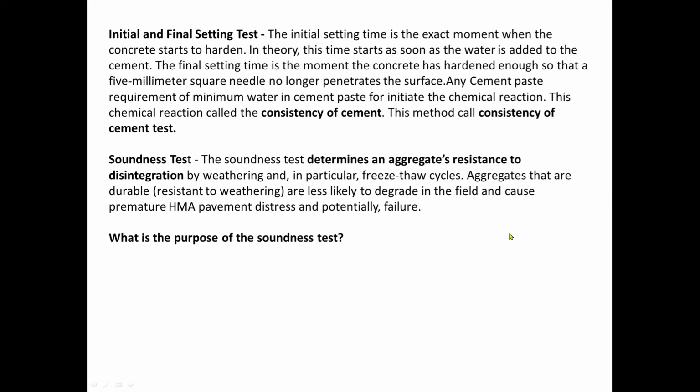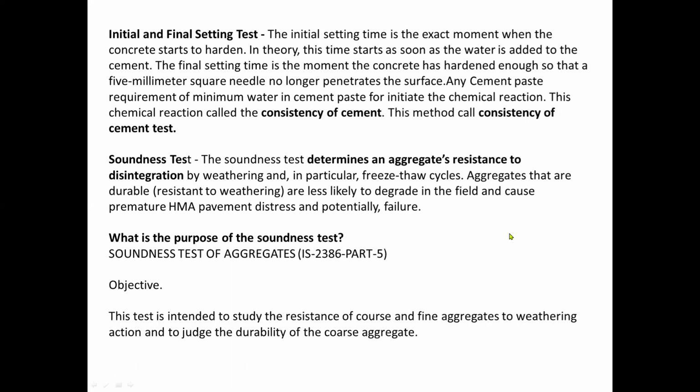What is the purpose of the soundness test then? Soundness test of aggregates by IS 2386 Part 5. Objective: this test is intended to study the resistance of coarse and fine aggregates to weathering action and to judge the durability of the coarse aggregate.